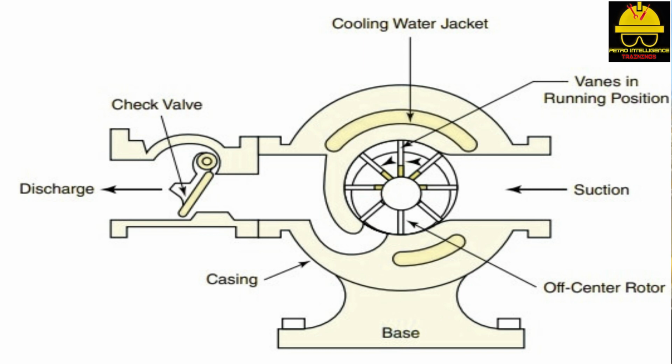Sliding vane compressors require lubrication between the vane and contact surface. Lubricating oil is injected into the suction side of the compressor. This procedure helps prevent internal slip and provides a positive seal. Sliding compressors are typically non-pulsing systems.